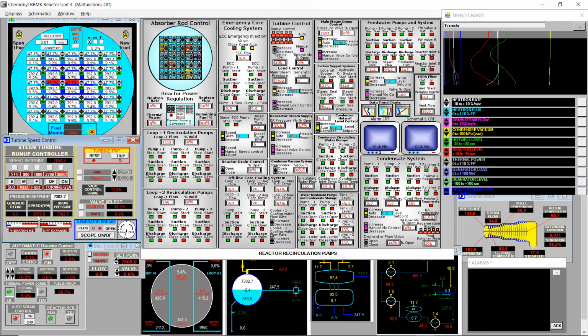Speed of the turbine at 2800. I will start closing the valve after 3000. I will close to 10%. And I know that we need around 4.5% of opening of the startup valve at this drum pressure to keep the turbine at 3600 RPMs. So let's anticipate for this and start closing, so we end up at this nominal speed at the correct opening.